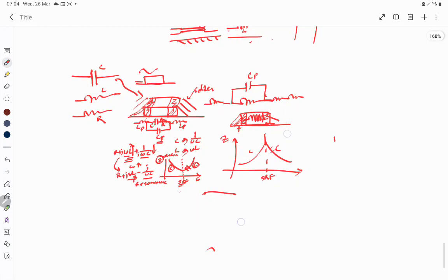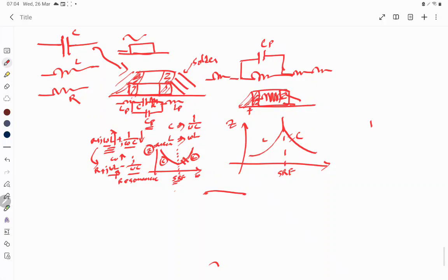So from this we can see it is very difficult to use a lumped component at high frequencies. Most of the SMD components, which are nominal 0603 imperial size, that is 60 mils into 30 mils, or say 0402 imperial size, that is 40 mils into 20 mils, stop working between 1 gigahertz and 10 gigahertz, and that is also only for components made particularly for RF.